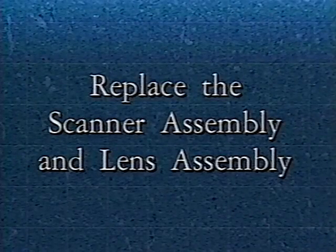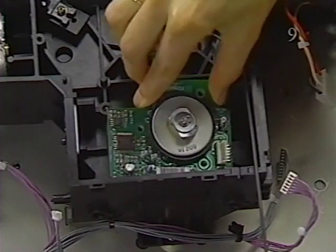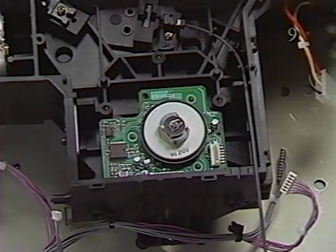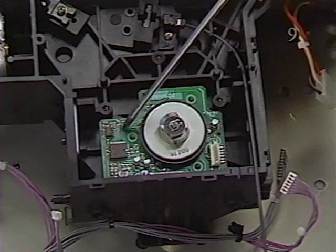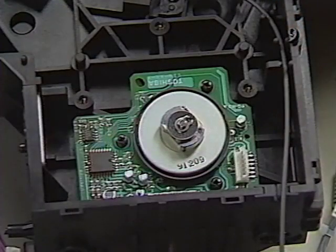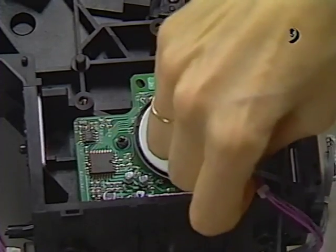Replace the scanner assembly and lens assembly. First, carefully lower the scanner assembly into position inside the scanner assembly case. Replace the 3 long black scanner assembly screws. Now reconnect connector J301 to the scanner assembly PCB.